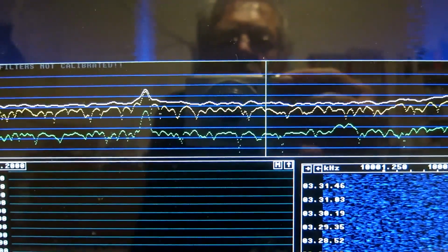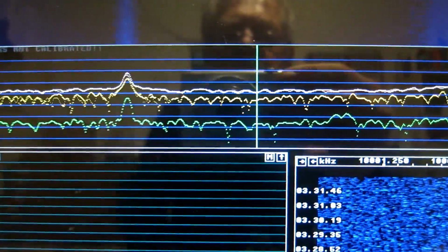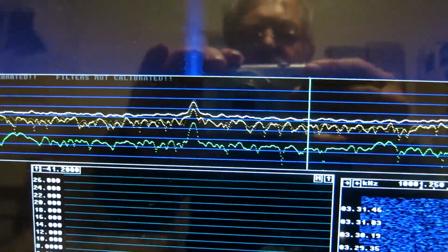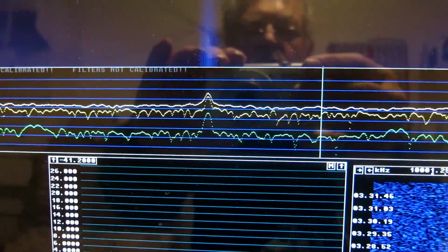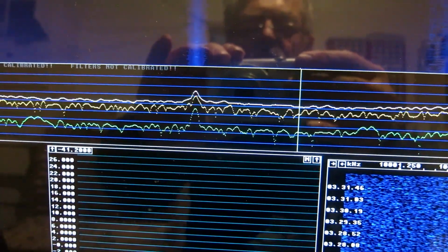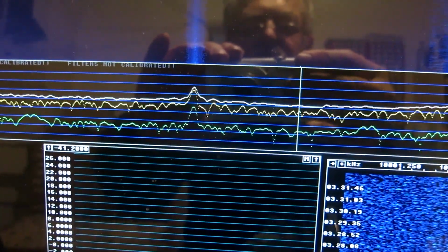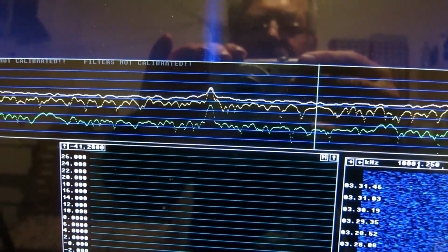So there is no correlation between the channels, or at least it is very small. And very close to the carrier, sensitivity is not as much an issue as at larger separations, because I don't expect the dBc per hertz to be extremely high here.